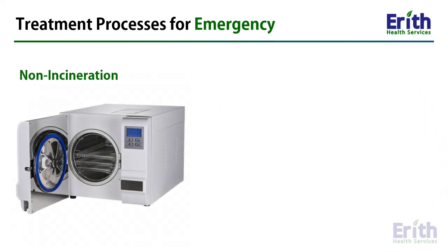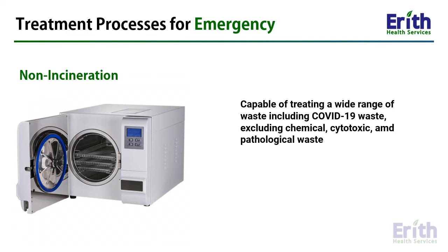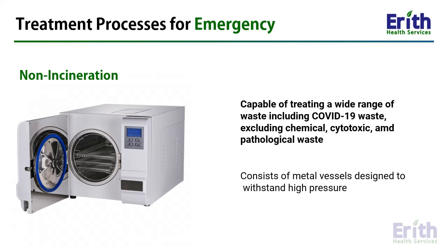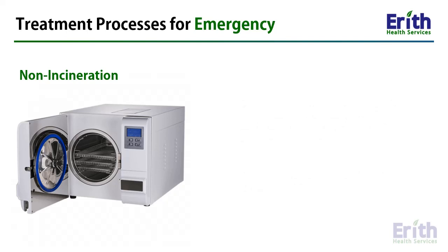Non-incineration or autoclaving. It is capable of treating a wide range of waste, including COVID-19 waste, excluding chemical, cytotoxic, and pathological waste. It also consists of a metal vessel designed to withstand high pressure with a sealed door and an arrangement of pipes and valves through which steam is brought in and removed. A typical autoclave operating condition of 121 degrees for 30 minutes must be tested using biological indicators.